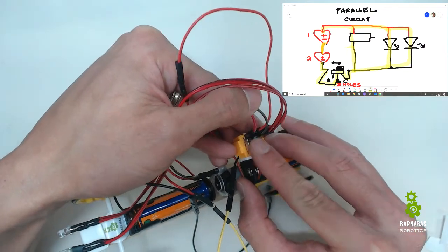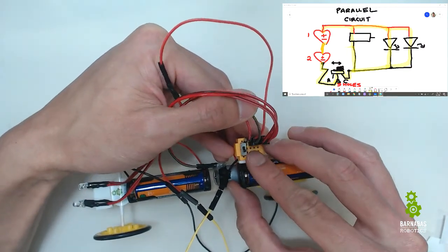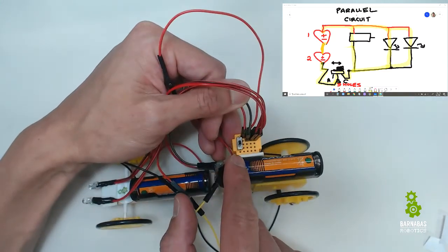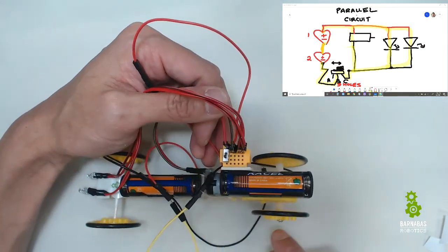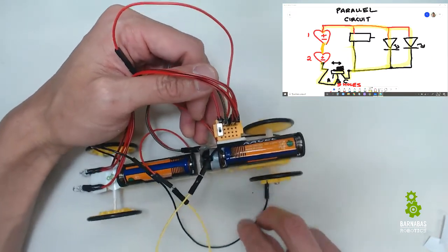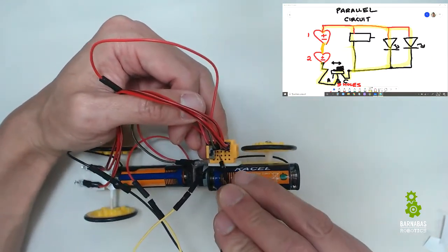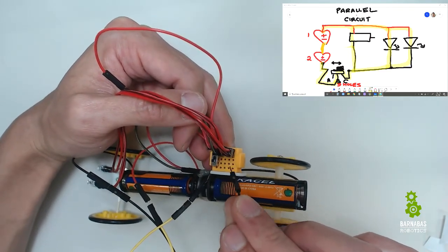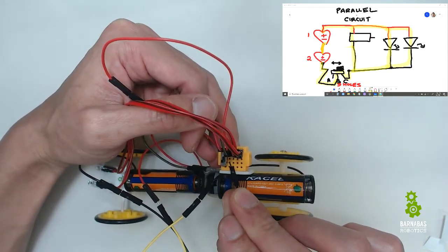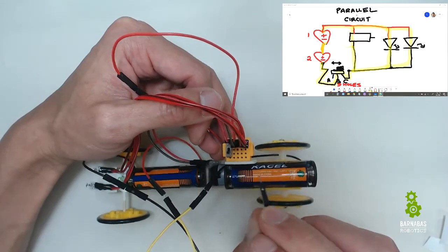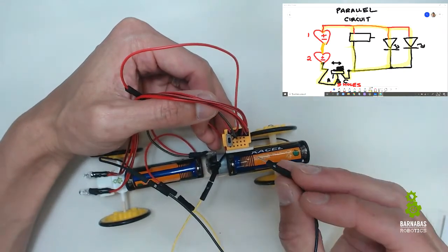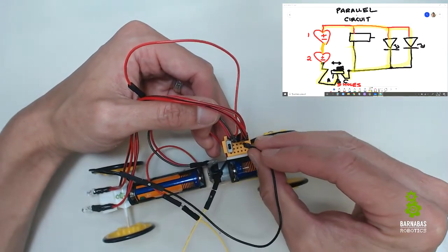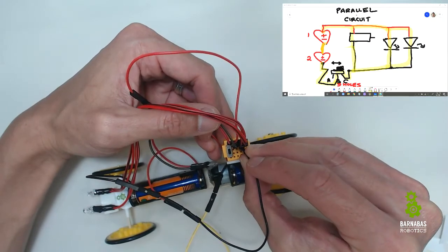Once you put it in, you should see one hole up top and one hole down on the bottom. Right now the middle leg of the switch is on a row that has nothing in it. The way I can tell that is that there's 4 empty holes next to it. So the middle leg needs to connect to the minus of battery number 2, so I put it right there. There we go.